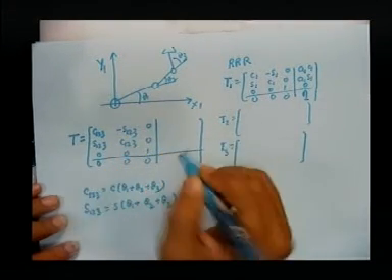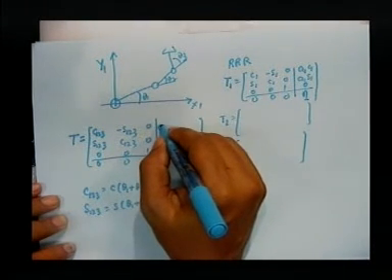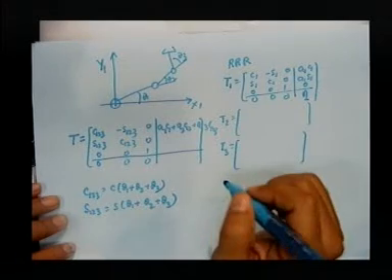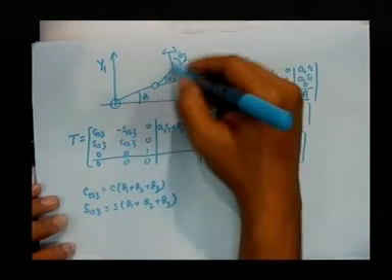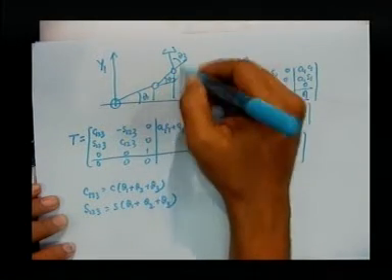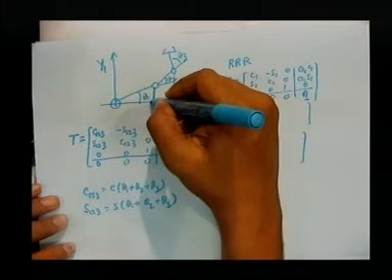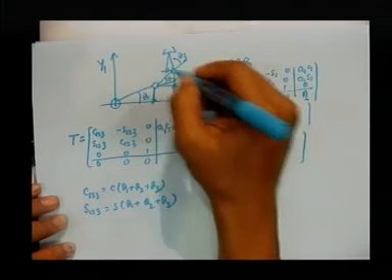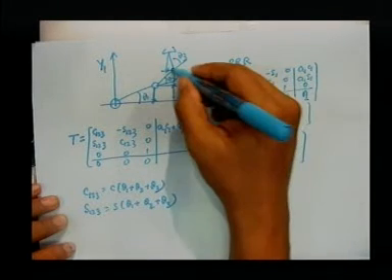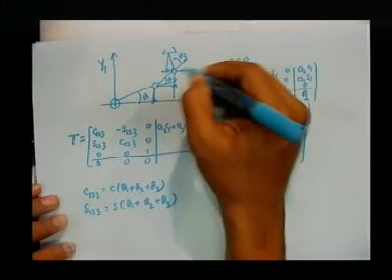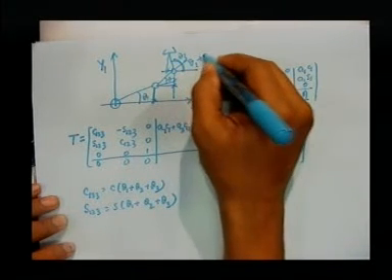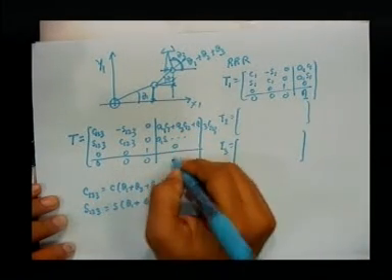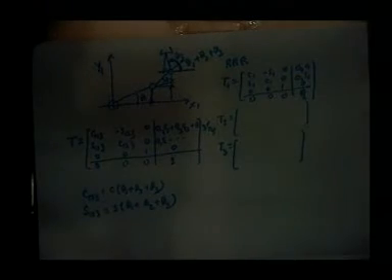Now, this portion will be like this: A1 cos 1 plus A2 cos 12 plus A3 cos 123. You must be wondering how quickly I have written it. Actually, I have looked at this diagram. Px is nothing but the summation of these lengths. This length is A1 cos theta 1, this length is A2 cos of theta 1 plus theta 2, and similarly this length will be A3 cos 123. Even though it is in the minus direction, this will be taken care of by the summation, because I am measuring the angle here. So, this is theta 1 plus theta 2 plus theta 3. Similarly, I should be able to write A1 sin 1 and so on, then 0 and 1. It is as simple as that. So, that was our planar.